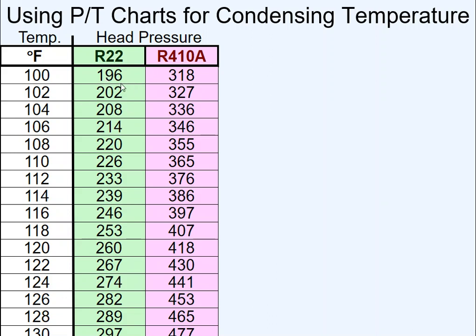So in this case, we already talked about R22, so let's say we're going to deal with R410A, which is a different refrigerant. 410A is a newer refrigerant that's found in almost every residential system that's out there. It's in a pink jug. It's a little more environmentally friendly, ozone friendly especially. R22 is actually in the process of being completely phased out. They're not making any more, so there is still some out there, but once it's gone, it's gone. So it's on its way out.